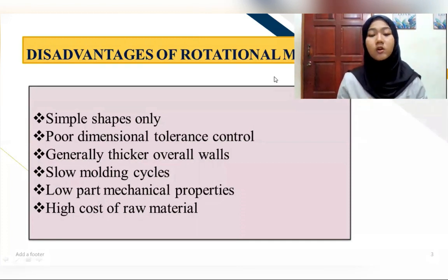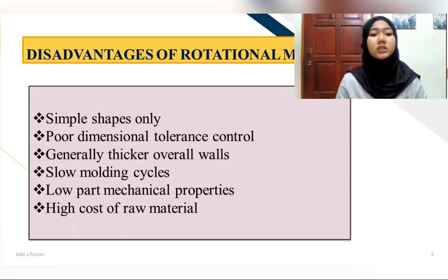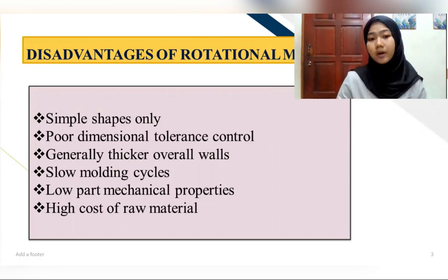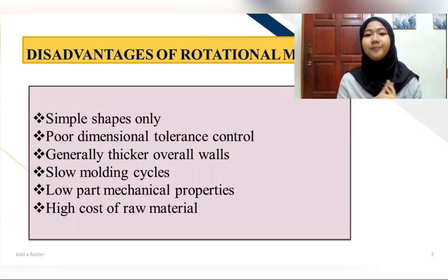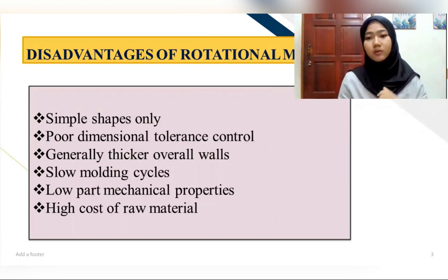For the disadvantages of rotation molding, we can use only simple shapes, limited dimensional tolerance control, generally over a wall, and slow molding cycle, low part mechanical properties, and the most sadly, high cost of raw material. Those are the disadvantages of rotation molding.